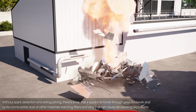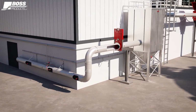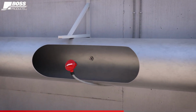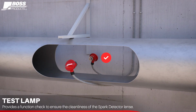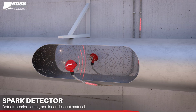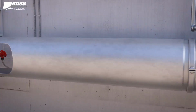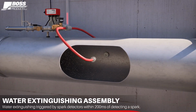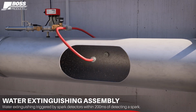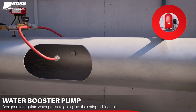Spark detection is basically where a sensor is installed in the ductwork, and when a spark passes by, it'll send a signal back to a control panel that will tell an output device of some sort, whether it's water extinguishing, a mechanical fire break shutter, or an abort gate, to trigger and basically mitigate the potential for a fire. So in this case, they're showing water extinguishing, which is something we can do as well, and provide booster pumps too.